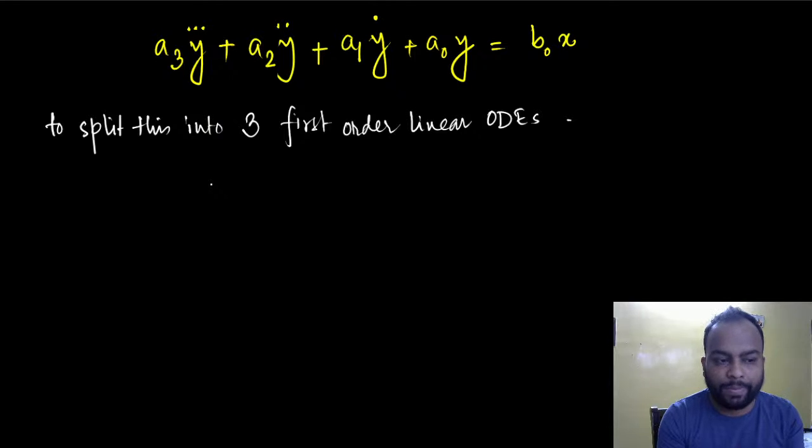It should not be ad hoc. But the transfer function modeling is pretty ad hoc. Depends on if you have this, then do this, then think about it, then do this. That is how transfer function modeling really works. But in state space, everything is so systematic that you have proper algorithms, proper ways that you can follow blindly, and you would end up with the correct result. This is how these things are designed.